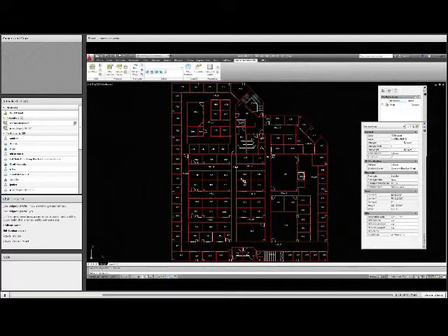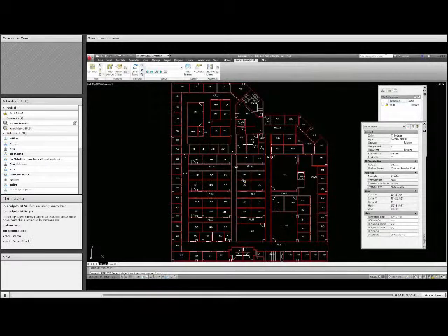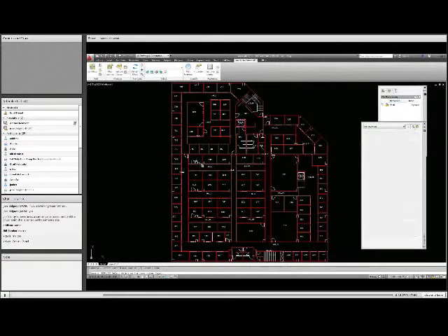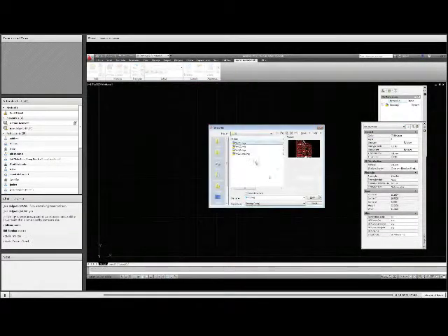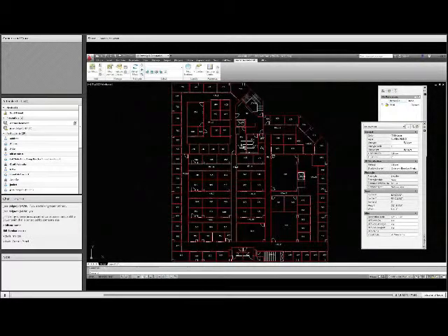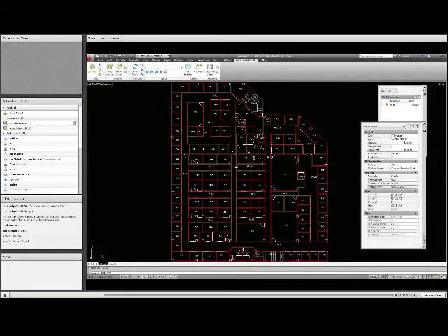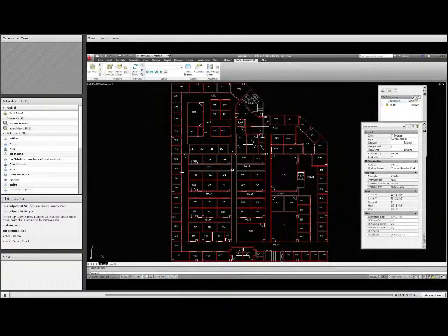And I now have my 3 feature classes for my architectural, my GSF, and my rooms. And the architectural, it's nice because we can very easily select all the layers that we want. My utility actually does an exception. I have a couple of layers I don't want to show up, like my room boundary lines. A few other layers like my grids, I don't want as part of the architectural line work. So we exclude those and it looks at all the layers in the CAD drawing, excluding those layers, and that creates a list of the layers that will be in the architectural line work.